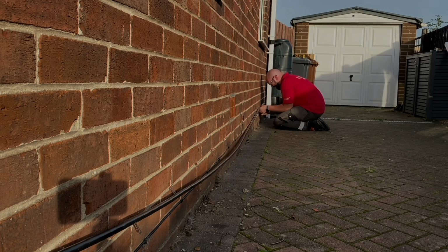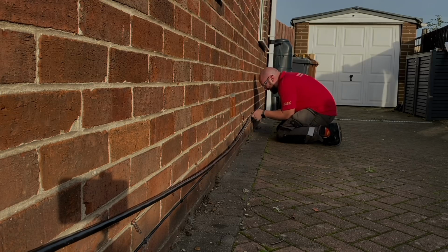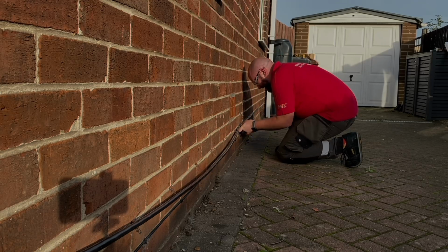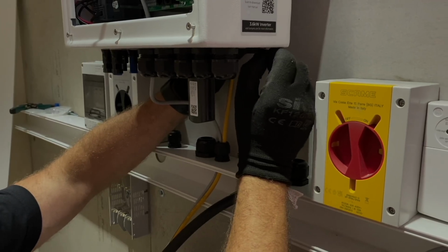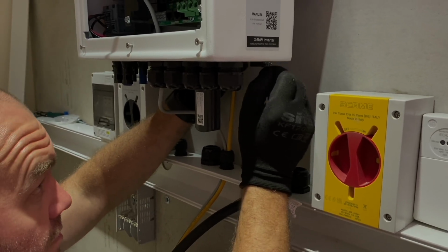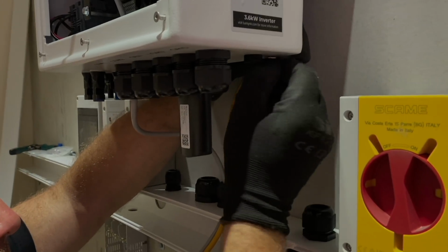So starting with the cable supplying the inverter. We can carry out a cable calculation to determine the size of the cross-sectional area of the cable needed. The manufacturer will also give guidance on the cable size. However, this does not account for cable length and volt drop, so we do need to consider that.